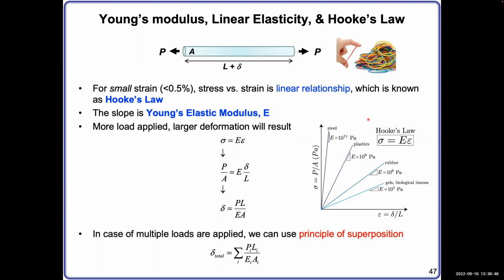Finite element can solve all those problems if the material has a complex behavior. But in the class right now, let's master the fundamentals first. We assume all the materials we are dealing with are elastic in this linear region. Once you know that stress and strain are proportional to each other and linked by Young's elastic modulus, we can write the definitions of stress and strain.